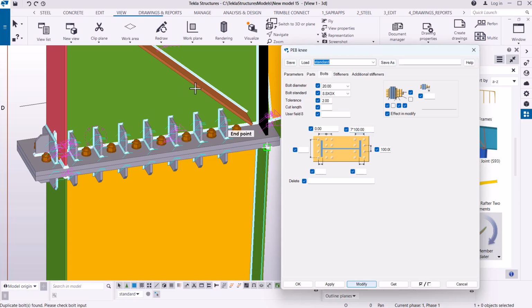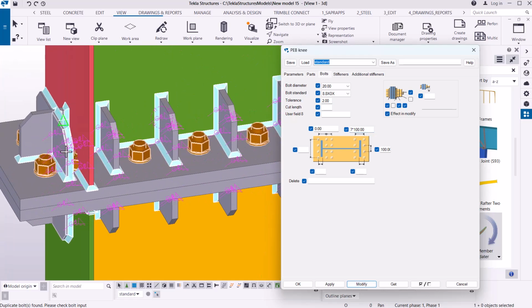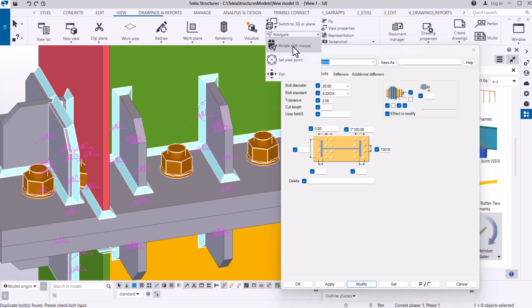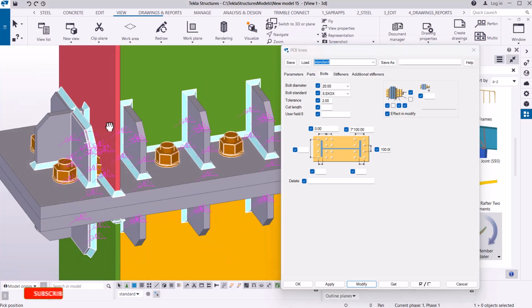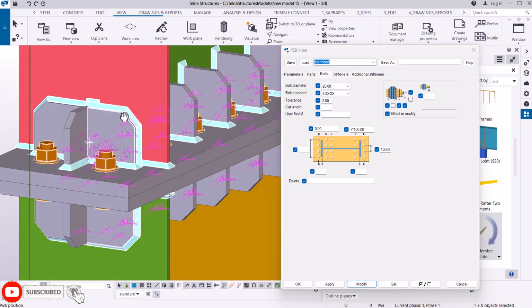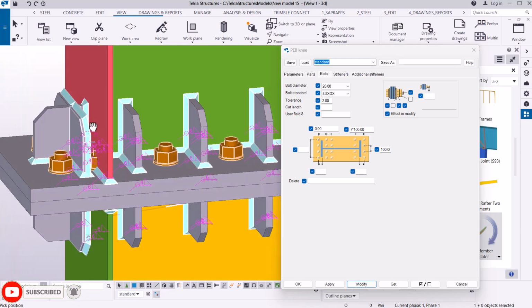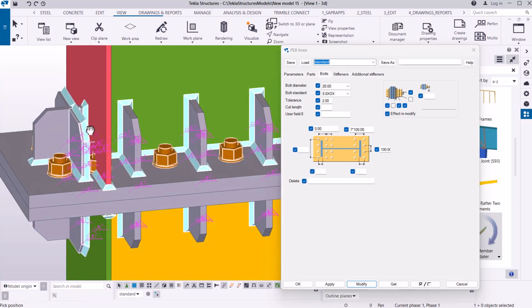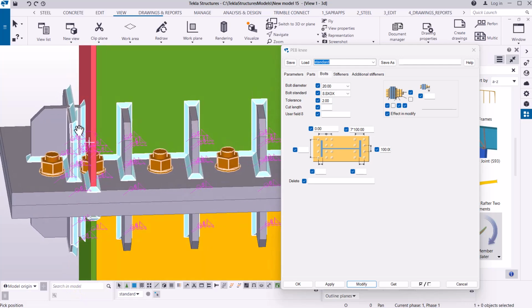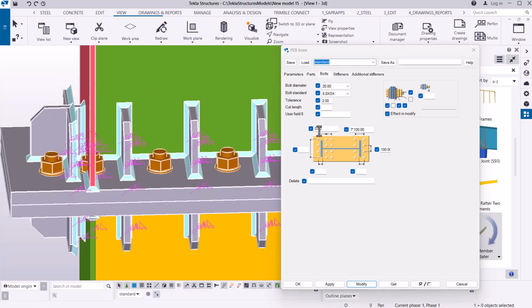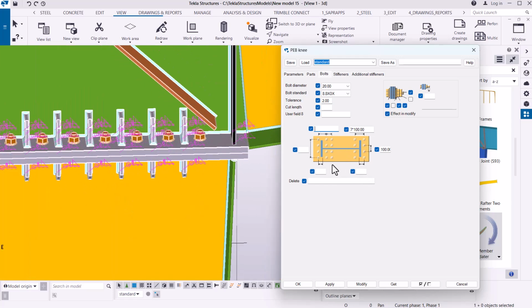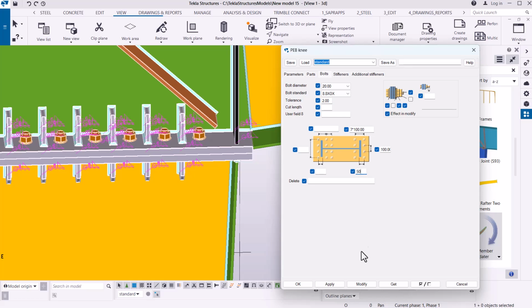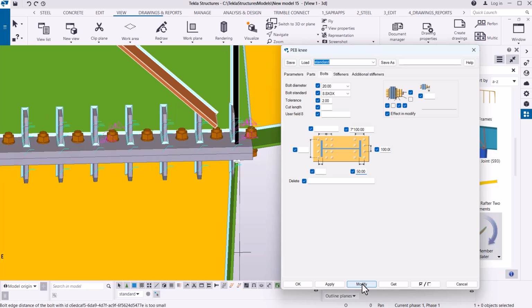You can see that, and you can see also we have some stiffeners here protruding outward, and this totally messes our objective. So we have to get rid of some stiffeners that try to mess our work. Now let me come here and click on interrupt and get rid of that and leave that space empty. And I'll come here and key in an offset of 50 here. Just type 50 right there and click modify. Once I've clicked modify, let's see whether that will be reflected.